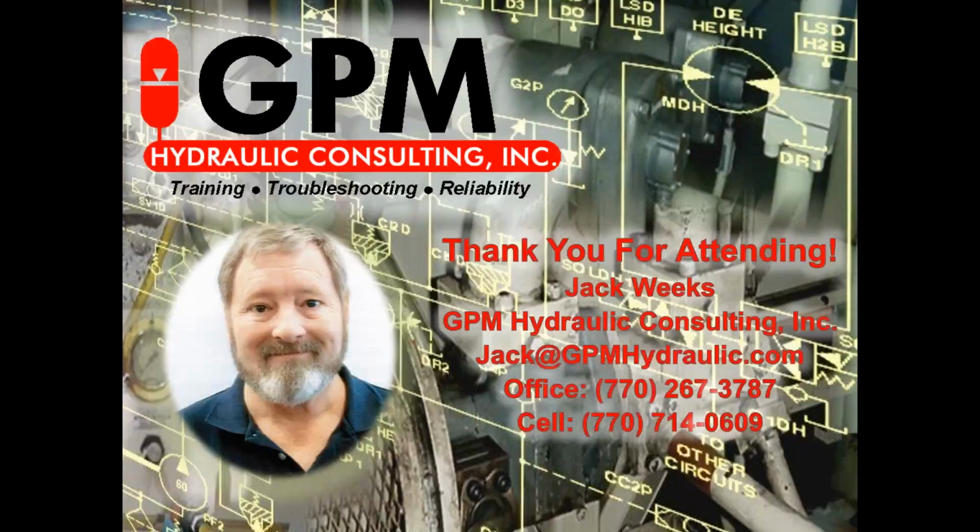Now, anything blocking the suction line could cause it. Most common cause is a plugged suction strainer, because they're kind of out of sight and out of mind down underneath the oil. But what happens here is the suction pressure drops so low that it will pull air molecules out of the oil. And these air molecules get brought into the pressure side of the pump, and the sound that you're hearing is the sound of these air molecules imploding against the pump.